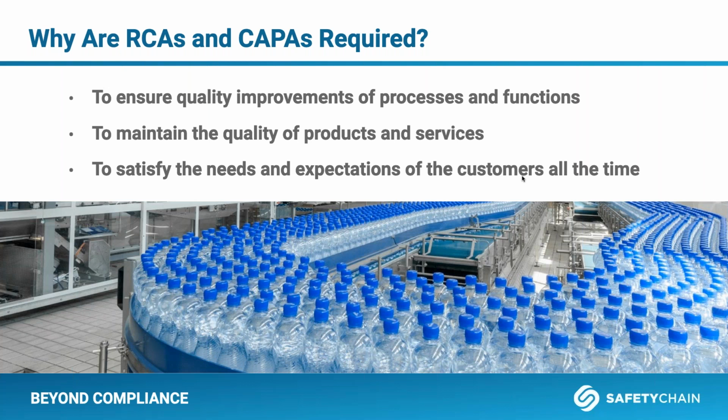How many manufacturing variances? If I look at your SPC information, statistical process control, in the food industry, and I know we have a lot of representatives from different areas, that's why I'm using examples from automotive and life sciences, and now I throw one in on food. Another one is giveaways. If I'm exceeding my weight limits beyond my upper control limit, that becomes giveaway or waste or scrap, something I am not managing. What's the root cause of that? Maybe it might be the equipment.